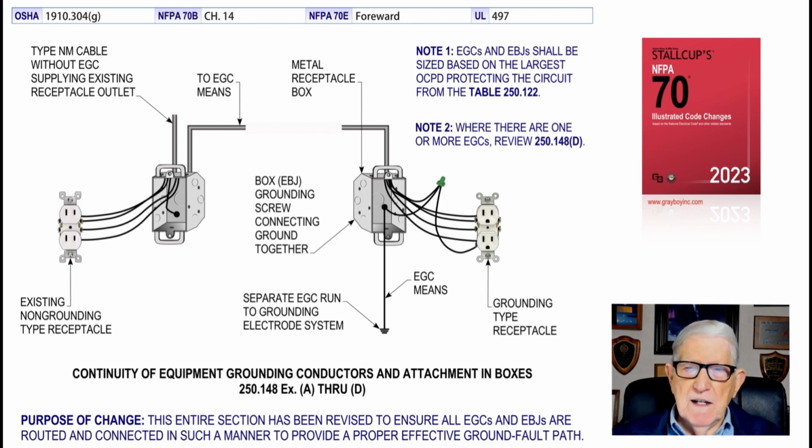Now, notice to the left we have a receptacle, so the non-grounding type. But if you had an equipment ground, it would still have to bond that metal box. And then, of course, if you had a metal strap, means would have to be provided to bond that in, like with metal screws, in most cases, that would bond that into the plate if it was metal to metal. And you'd look at that, I believe, in 250.146(A), if I'm not mistaken. It's either 250.146 or 250.145 that we find those rules.